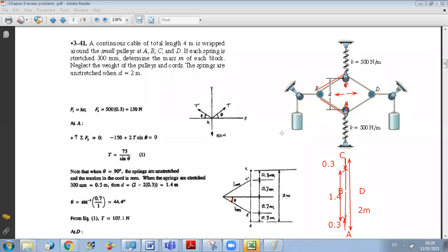But doctor, where did we use the angle theta when we calculated it? We use it afterwards for the projection of forces. So when you write sum of y at A equals 0, you need this angle. You need it at A and B. So when we consider point A, when you do sum of y, you should project your forces. So you should know this angle.